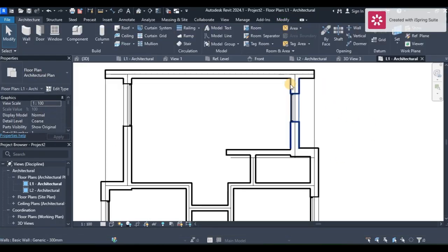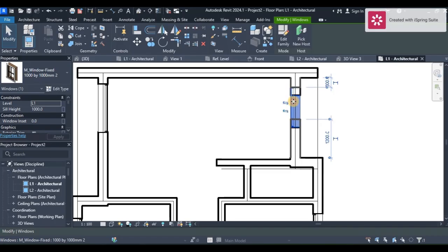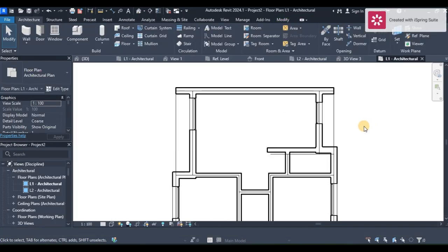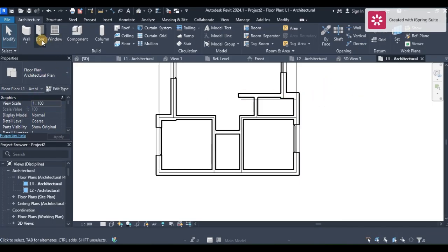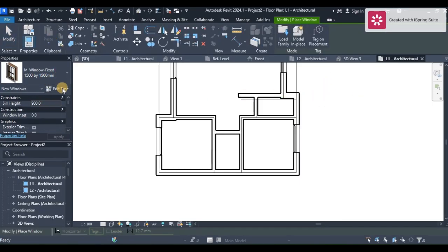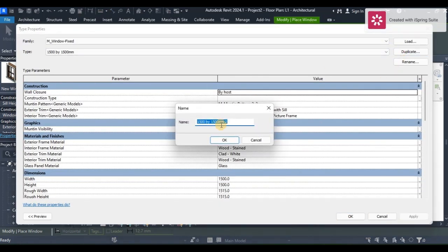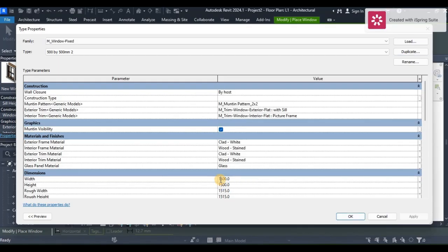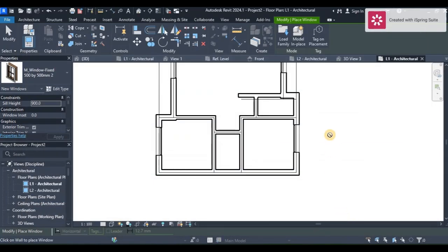So with that done, now I can just push it a bit somewhere there, and now I can put the ones for my bathroom. So I'm just going to go back again and do the same process, duplicate the first one and just edit the size to 500 by 500 for my bathrooms, and then I'm going to press OK, and we're going to edit our height and our width here. So just as simple as that, and then remove it, and then we apply and press OK. So that done, I can now place it on my bathroom areas. It's going to have one here and one here.